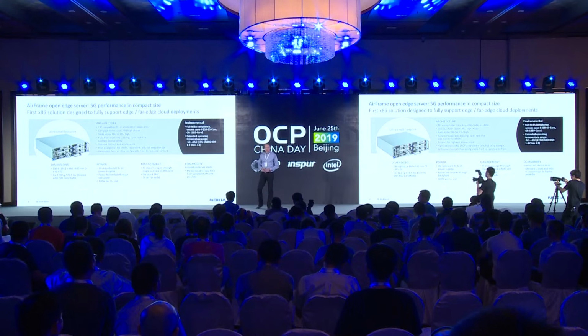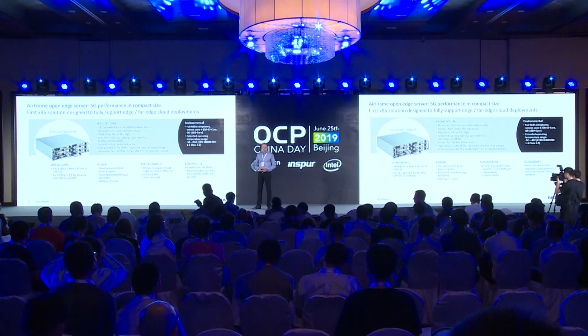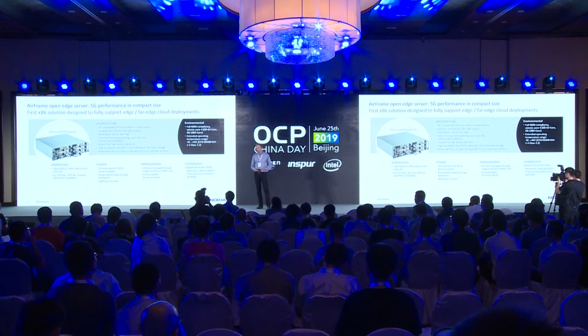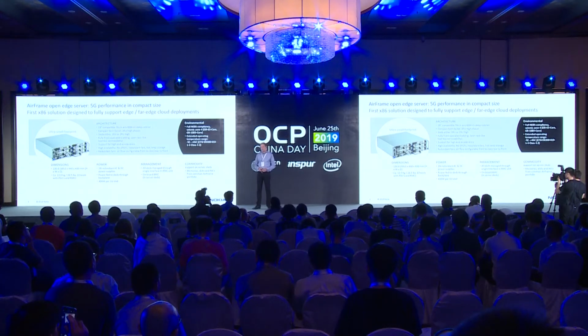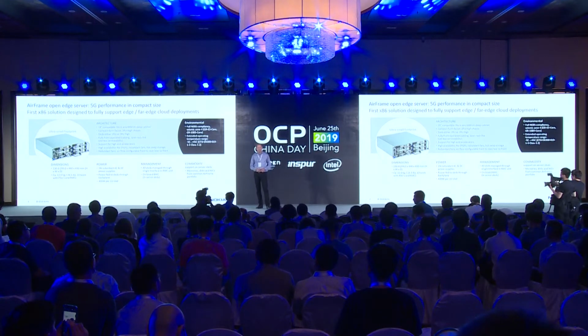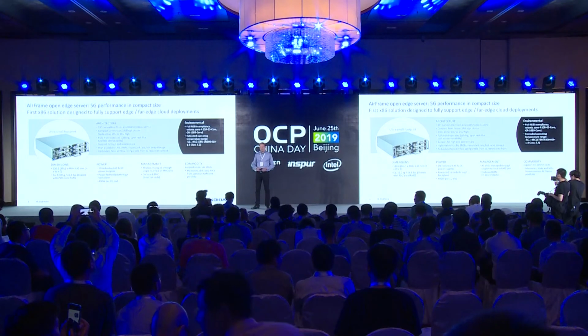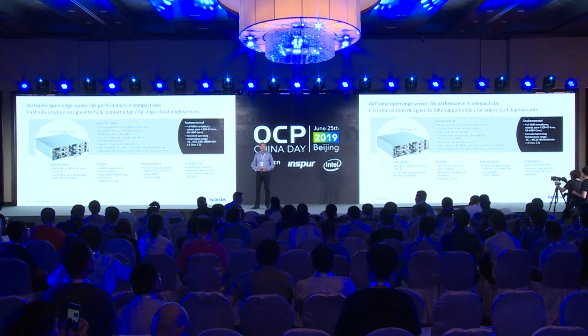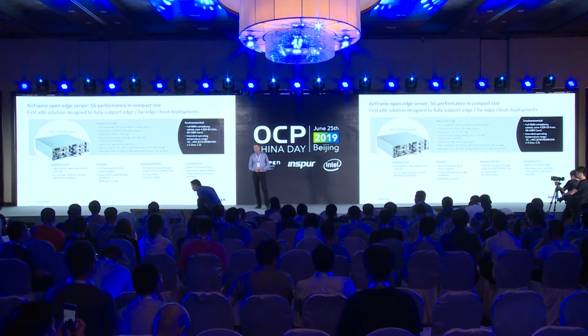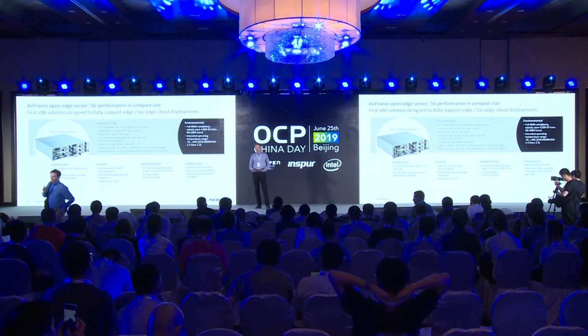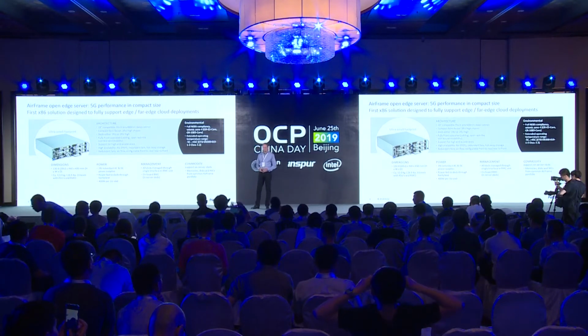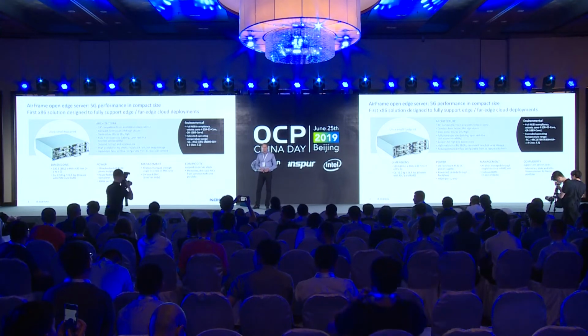And there may be varying kinds of power feed available at these sites. So AC and DC are supported, and the different flavors of one-phase and three-phase solutions can be supported by using different power delivery units. Also, the power feed capacity can be limited. So the solution needs to be modular and scalable, so that we can start with maybe a couple of servers, or scale up to a full rack, or even several racks when that makes sense.